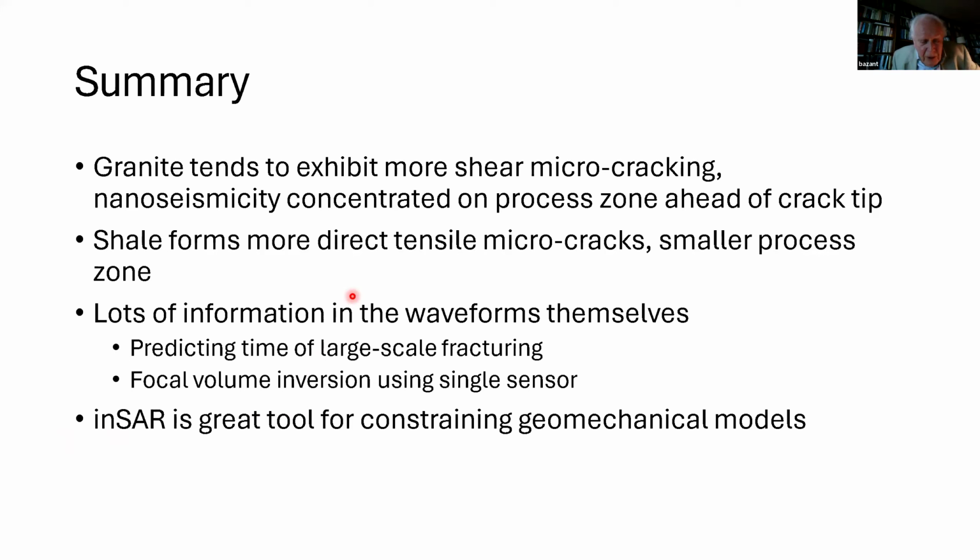First of all, Dr. Lee, excellent work and excellent presentation. But there is one significant consequence of the GAP test that we developed at Northwestern University, which shows that under crack-parallel compression, which is non-singular, uniform, the fracture process zone changes enormously. The process zone also changes shape.